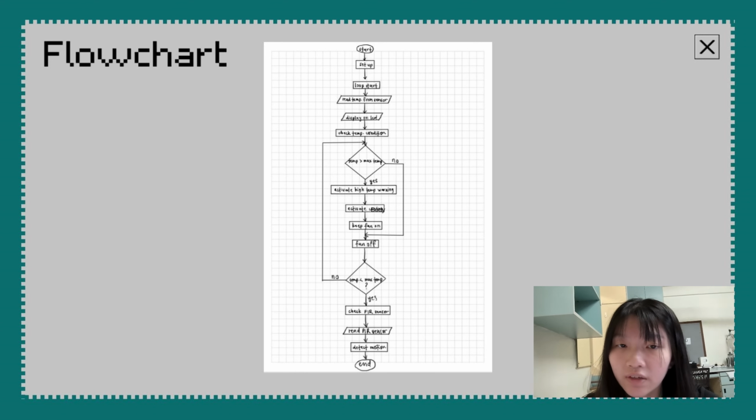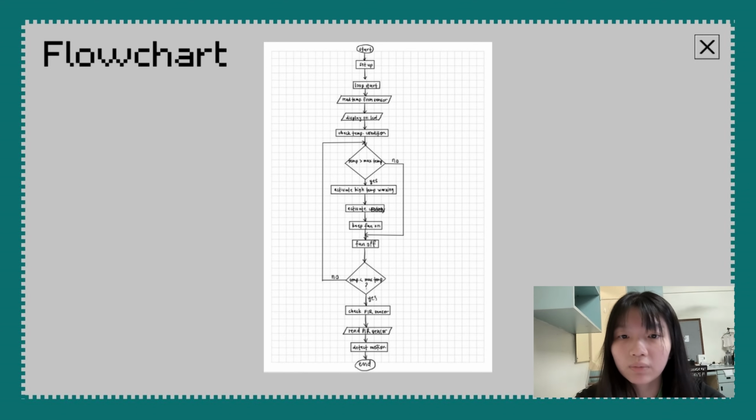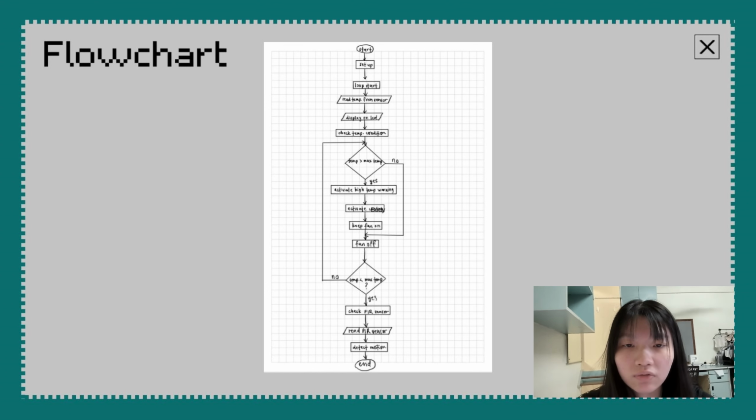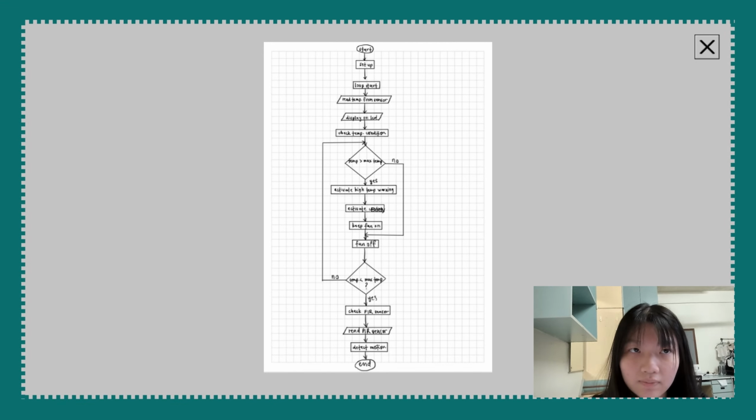Now, is the current temperature lesser than the maximum temperature? If it is not, the entire process will be repeated, and if yes, proceed to checking the PIR sensor. The PIR sensor is read to detect any motions, and for instance, we can detect heat energy in the surroundings.